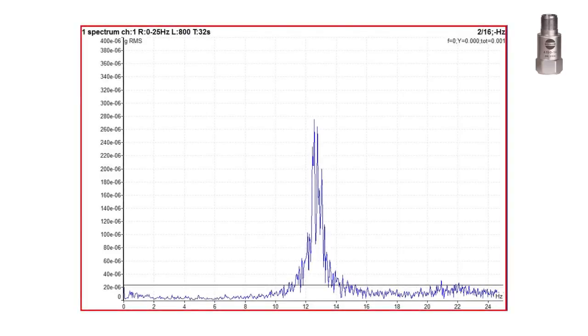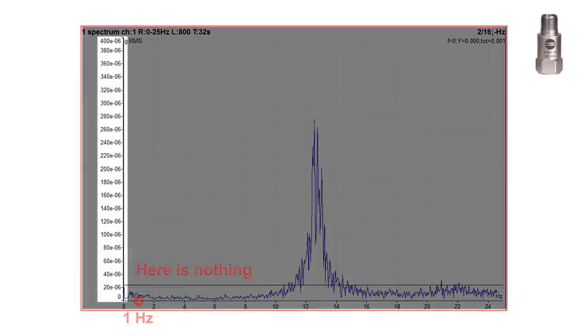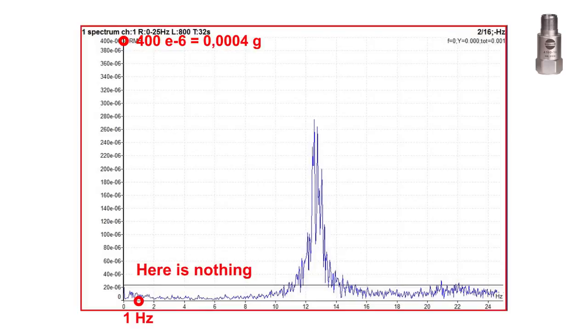On this picture I measured spectrum in 25 Hz range only. Repeating frequency of shocks is around 1 Hz. You see nothing on 1 Hz. And again, notice very low acceleration level. The shocks do not contain energy. If I want to see the repeating frequencies in spectrum, then I must apply the demodulation. It means I must add the energy. Demodulated spectrum can display something visible.